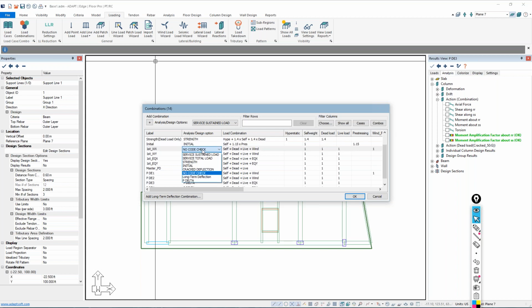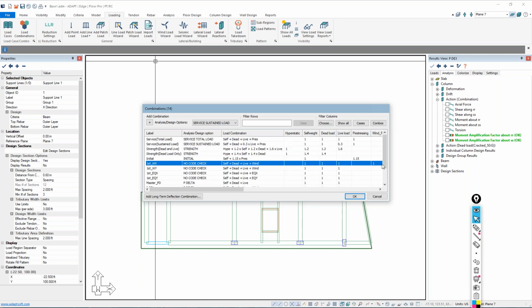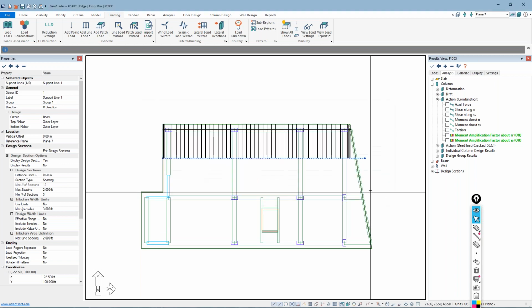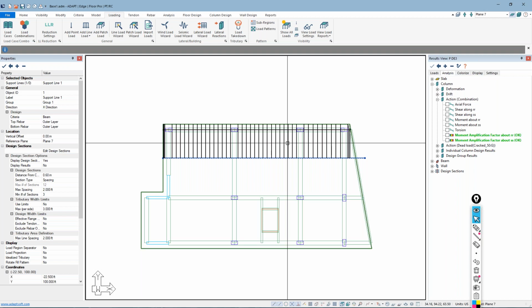If I change these load cases to strength, then I would actually get a design for the presence of the lateral load effect for first wind, first Y, EQX, and EQY. And so if we needed to include those combinations for the design of these frame lines, then we have to build out additional combinations in this example. I could produce results for those combinations.